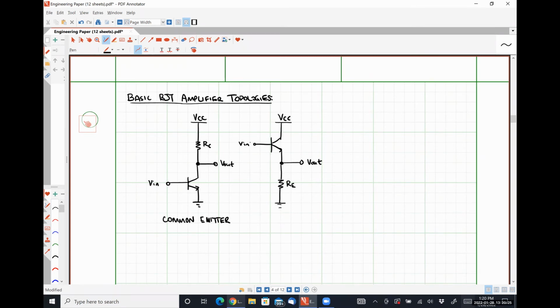So right now it says it's at VCC. When we do our small signal analysis where we turn off all of our DC sources, that VCC looks like ground because VCC is set to 0. And so we would see that the collector terminal is at ground, so it's a common collector amplifier.